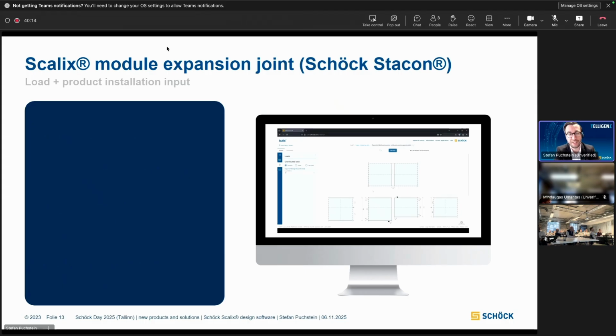After that, we have to go on and provide the system with our loads and, of course, some additional information. What you have to enter here for your loads is the design shear forces VED along the joint. We have to calculate those shear forces on design level, as I said, by yourself in your FEA software, or however you want to calculate them. After that, you input the data here in the software, and it will calculate the shear forces for all the dowels that are used in the calculation phase.